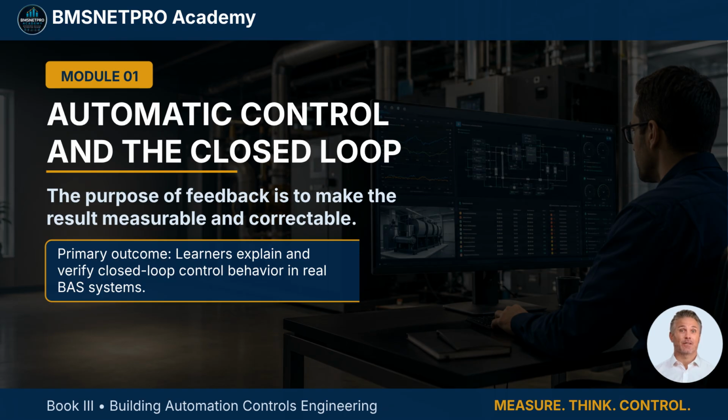We will identify each part of the loop, separate command from proof, and learn how to recognize saturation, loss of authority, and broken command paths. Think like a field controls engineer. What did we request, what moved, and what result did the building actually produce?